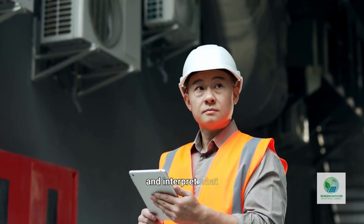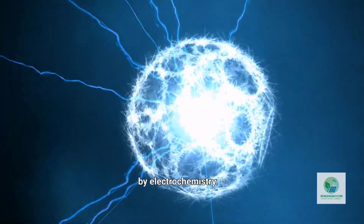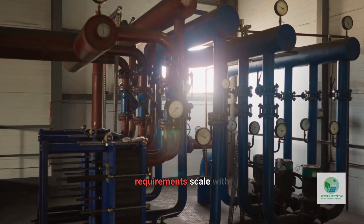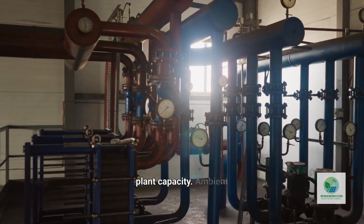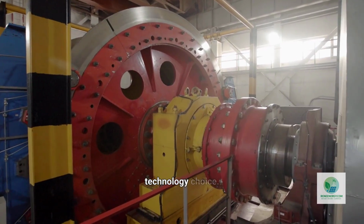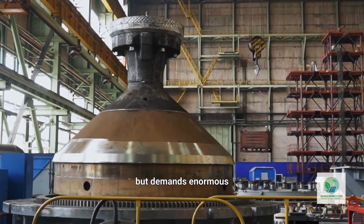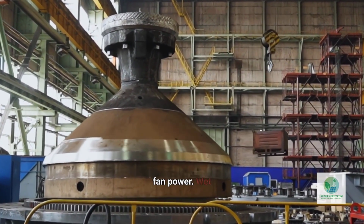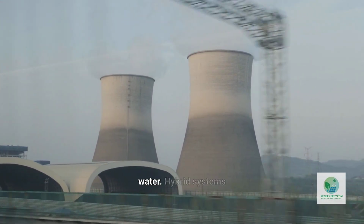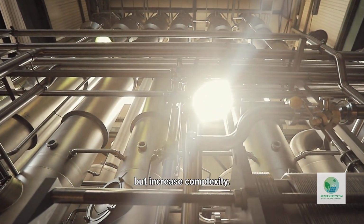Now step back and interpret what we have learned. Heat generation inside electrolyzers is dictated by electrochemistry. It scales with current and overpotential. Cooling requirements scale with stack size and plant capacity. Ambient conditions constrain heat rejection. Water availability constrains cooling technology choice. In hot climates, dry cooling reduces water use but demands enormous surface area and fan power. Wet cooling reduces surface area and flow rate but consumes vast amounts of water. Hybrid systems balance annual optimization but increase complexity.